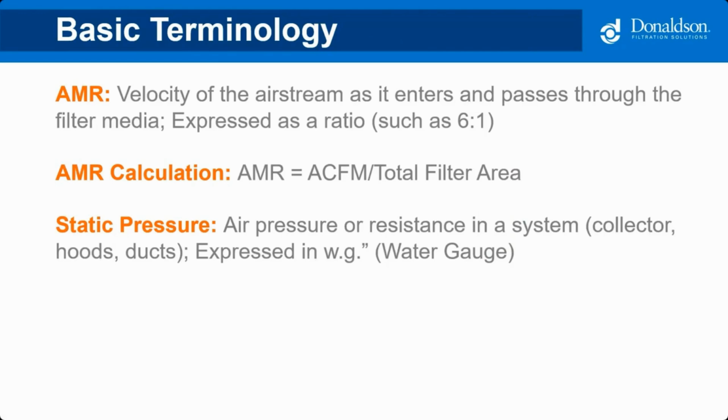And the last basic term I wanted to talk about is static pressure. It's resistance of airflow in a system from things like the collector, the filters in the collector, which will create more resistance when they're dirty, the hoods, and the ducts. So static pressure is a critical factor to take into consideration when designing a system.